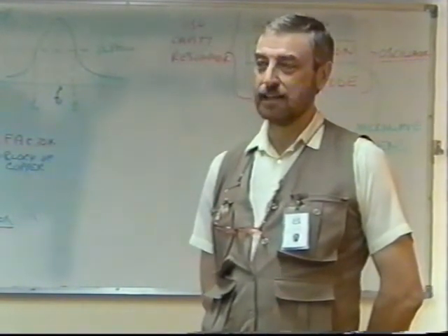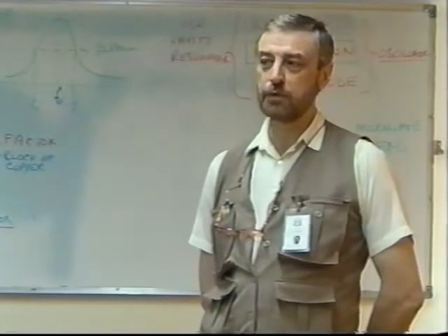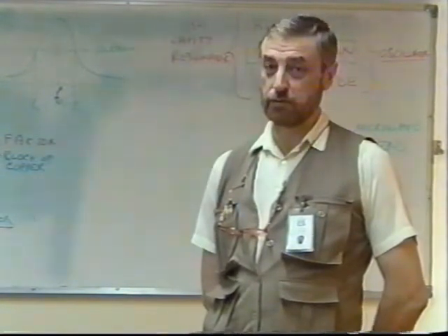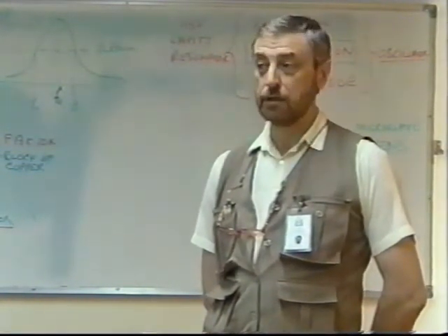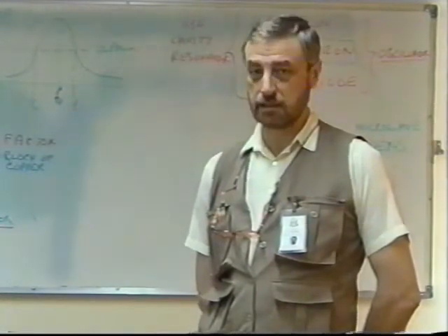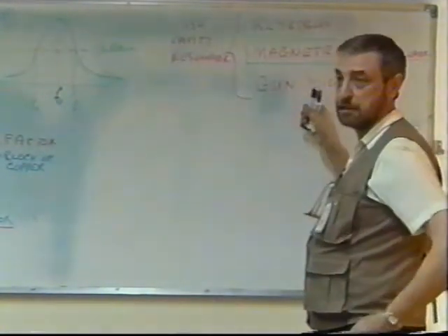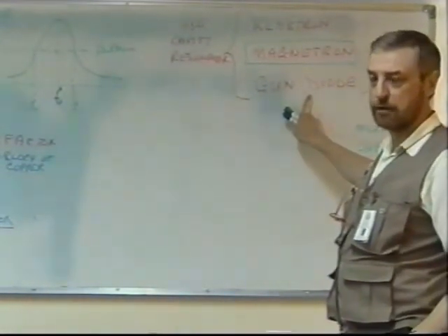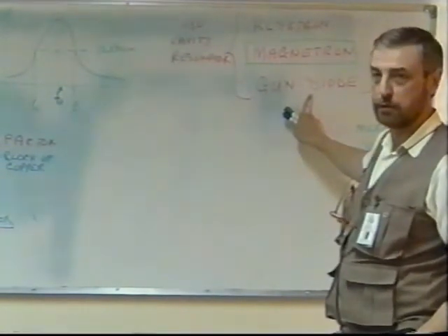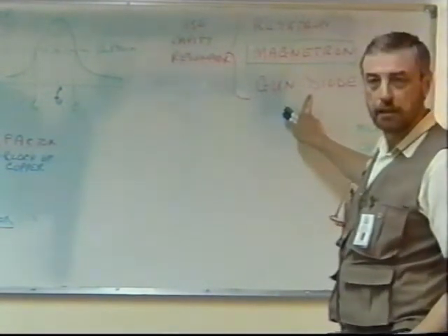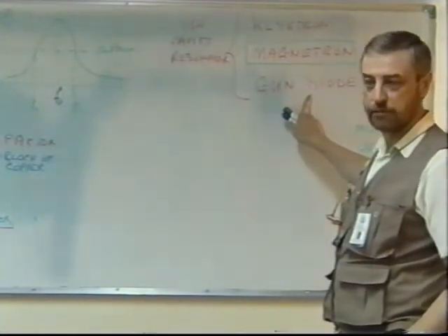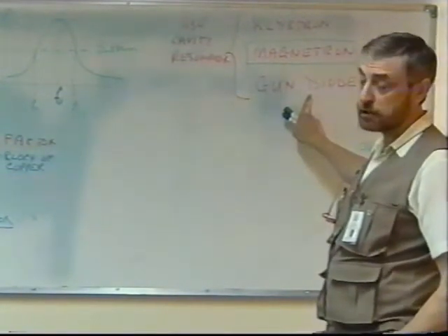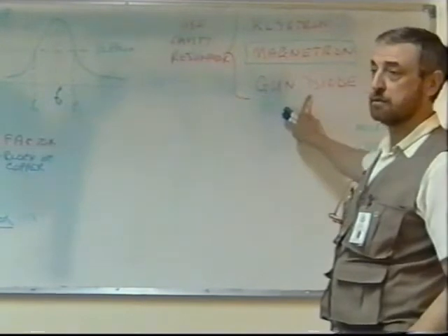Right. But if you were to go, for example, to the mast, to the microwave dish for our point-to-point microwave link, you will see in there you have cavity resonators. Both sides. They would actually use Gunn diodes, the semiconductor Gunn diodes. Quite low power, these things, though. Perhaps in the order of milliwatts. And it's the same with the receiving antenna for TV. You have an LNB which also has an oscillator in it. Although it's not a transmitter, it will have an oscillator and it will have this sort of device.